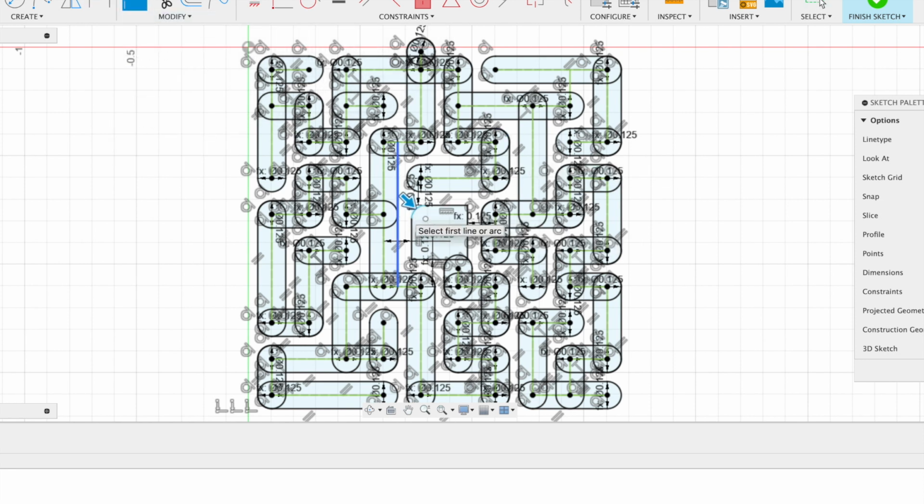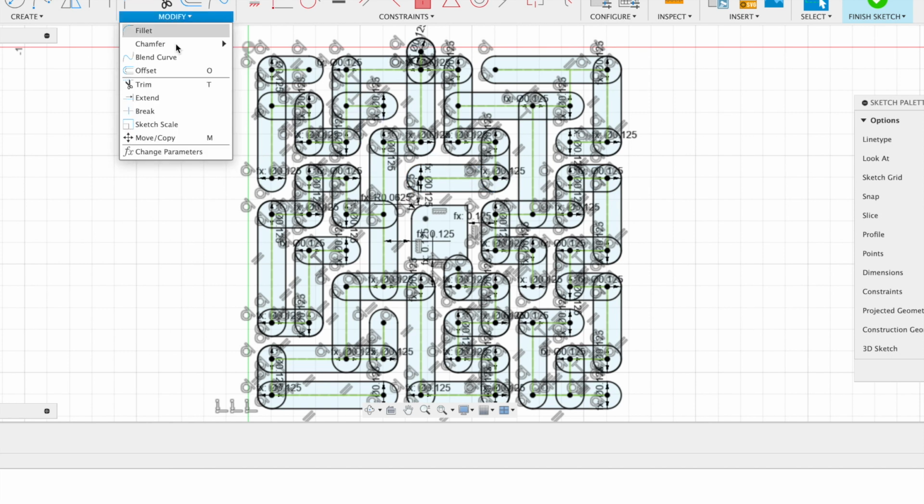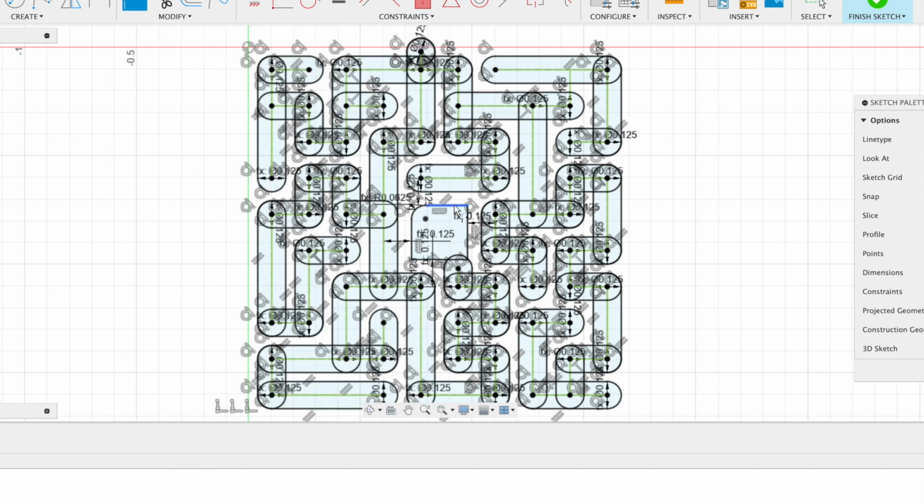Also, put a fillet that's half of D1 or 1/16 of an inch, and that will make it look nice. In this case, I only filleted 3 of the corners, but I'll come back later and I'll do the 4th one. The reason being is that I needed to be able to machine that pocket deeper, and I wanted a uniform corner.